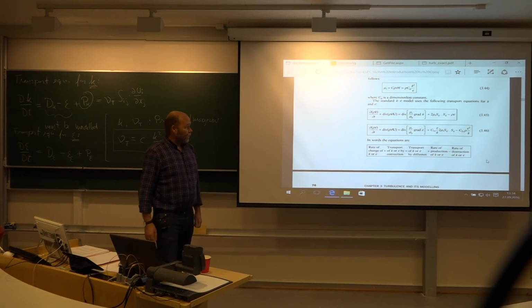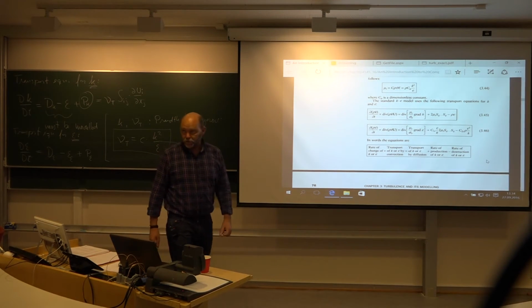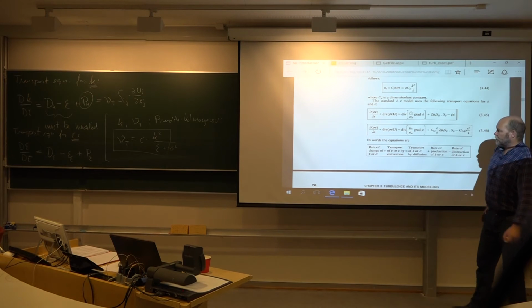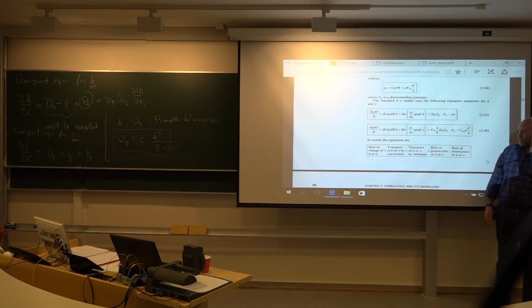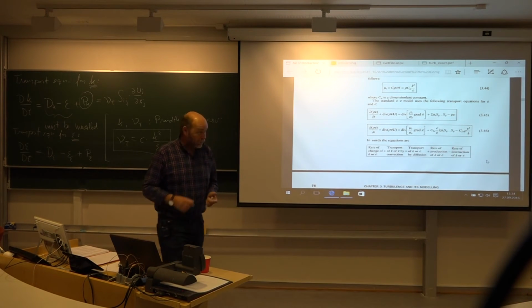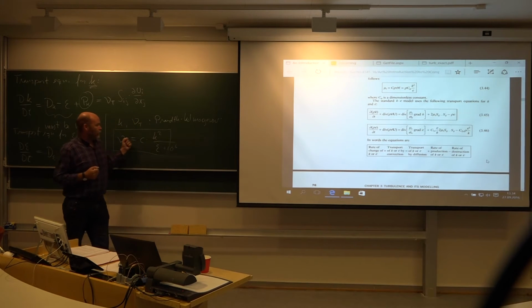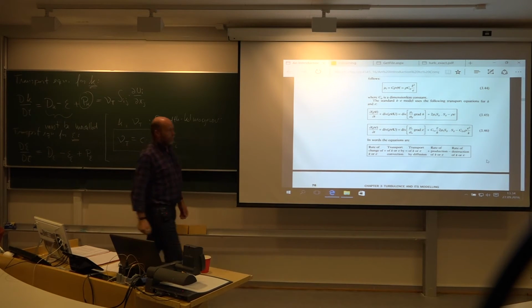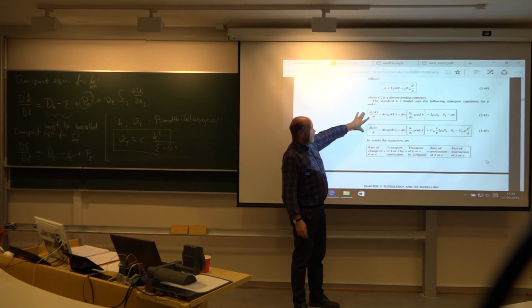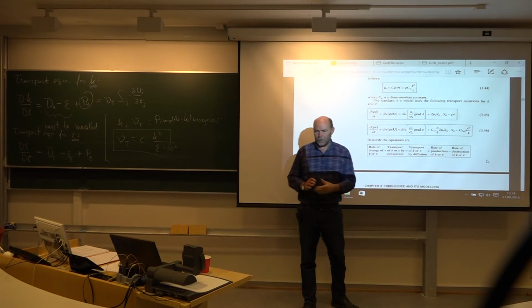This was k epsilon. Any questions so far? So you have the Navier-Stokes plus 2 additional transport equations. So it's a little bit expensive, of course, with regards to CPU, and it's a high Reynolds number model. Should be very high because of this, not happy with laminar flow. So for low Reynolds number problems, still turbulent, but fairly low Reynolds number, you shouldn't use the standard k epsilon. Then you have special models with low Reynolds numbers.